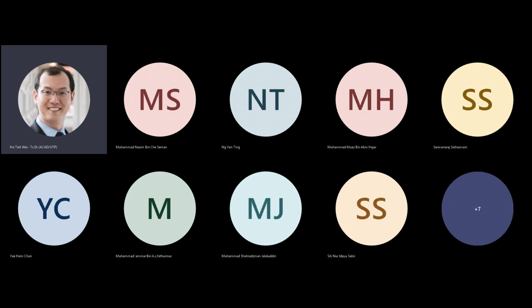You also can have something called the majority gate, where the gate is trying to determine, out of an odd number of inputs, if the majority are logic 1, then the majority gate will give a logic 1. Then you have a minority gate and so on. So there could be very custom designed gates which are more efficient to implement with CMOS logic, complementary MOSFET logic, and these form a basic set of logic gates which are available to you at the design.